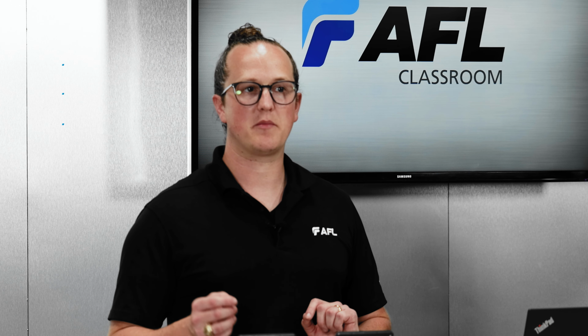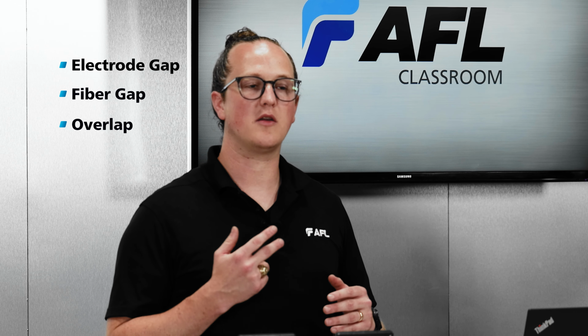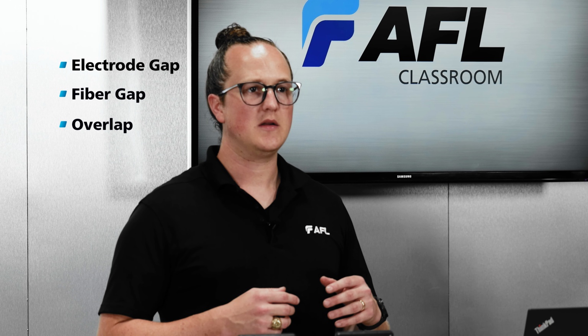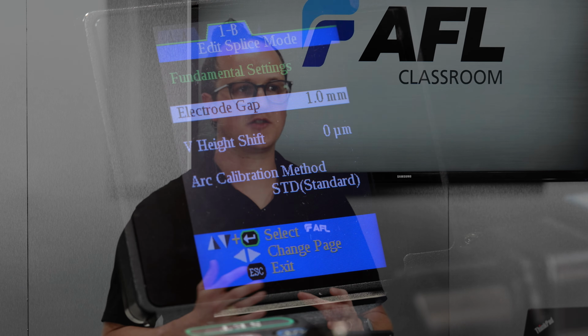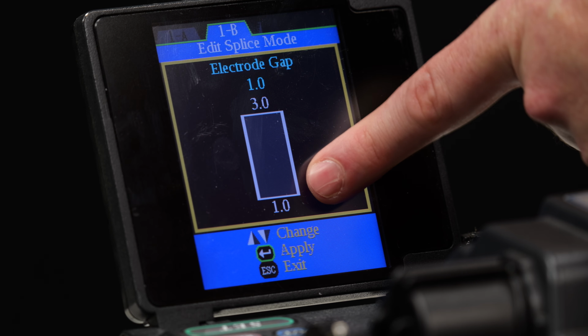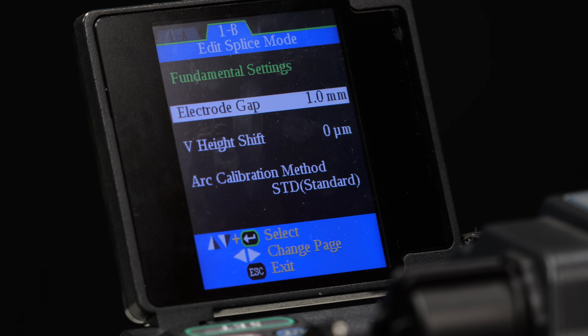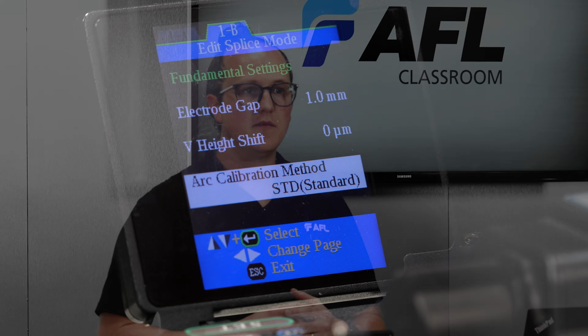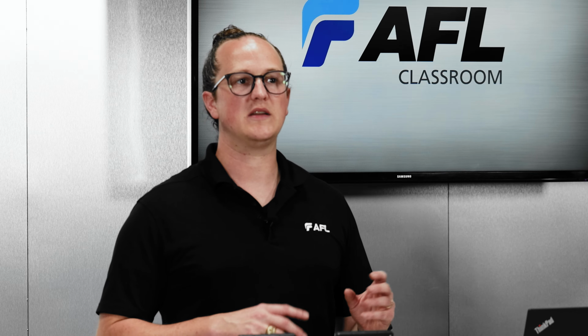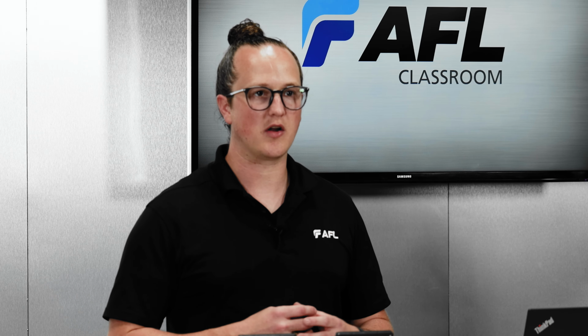After tuning in the prefuse, we can move on to the rest of the splice parameters, but the three key parameters to investigate here are the electrode gap, the fiber gap, and the overlap. As mentioned in a previous video, the electrode gap is primarily a function of the fiber's cladding diameter. So at this point in the optimization, you can tune in the electrode gap if it makes sense to change the size of the heating zone. Keep in mind though, that this will reset the arc calibration's accuracy and require you to use the special arc calibration method.